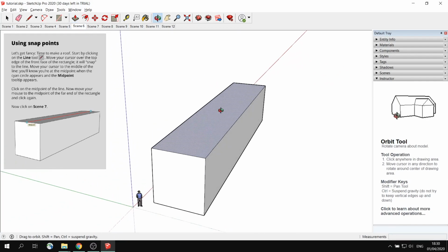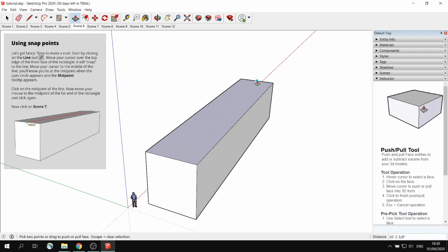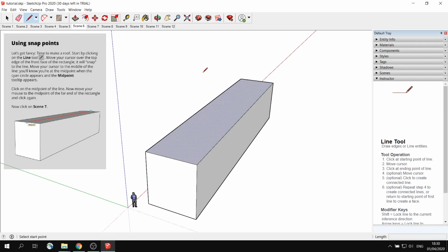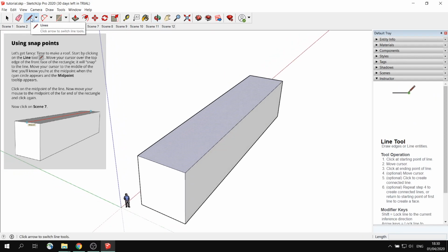In the next step, we're going to create a bisector from here to here using a line tool. Okay, so I selected the line tool, and notice how when I move around the line tool, the highlight slightly changes. So on corners it snaps and becomes green, in the middle intersection it becomes blue, and whenever it's not aligned to anything, it's red. So I just want to do the perfect midpoint intersection, a bisector, so from here to here.